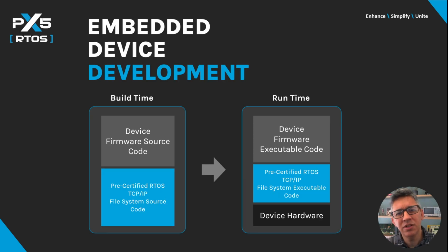The functional safety of a typical safety-critical device can be viewed from two different perspectives: the build time and the runtime. Let's start with build time, which is the phase during which all device firmware, typically written in C and assembly, is compiled, assembled, and linked into one image that will be flashed to the device. Once loaded, the device powers up, and then the device executes the firmware image. The execution is what is called the runtime.